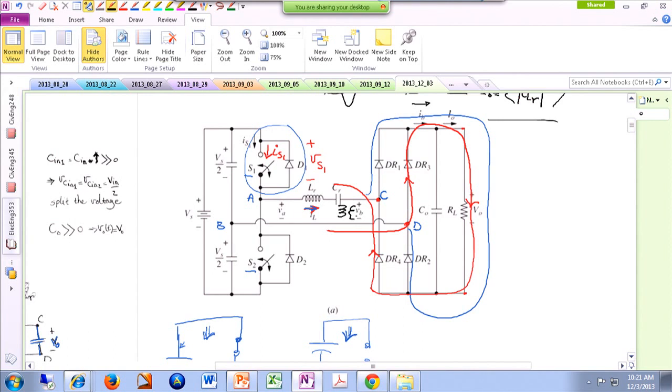And you need a resonance going on, because whenever you have a transformer, you better apply a purely sinusoidal signal to that transformer. For that sake, to minimize the losses, you are using this weird-looking resonance converter. So on the cell phone side, you have this side of the network, and this is basically the battery of your cell phone. And then on the base side, you have the first half of the system. So topologies like this are becoming very popular these days, because there's a lot of money being invested in wireless transfer of power for a vehicle, for a cell phone.